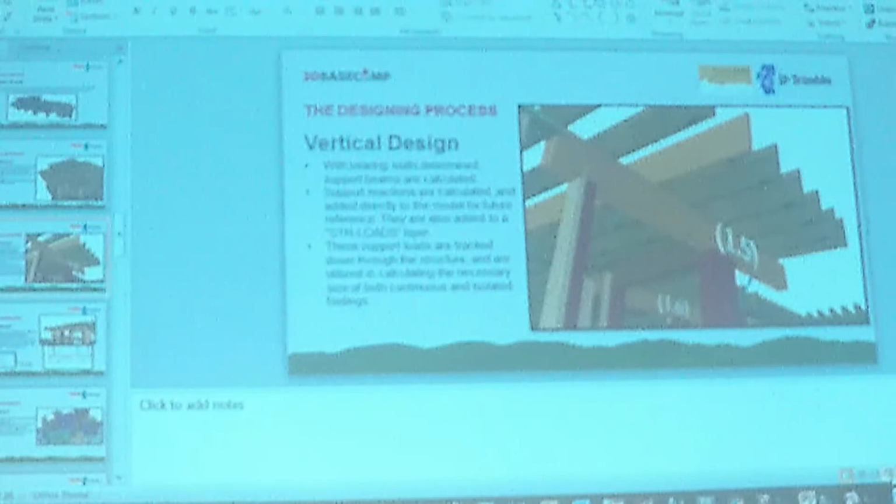All right, back. Hold on, right here. You put all the layers on one layer, layer 0. I saw it just then. Yes. Do you rebuild your layers, or do you just do that for structural analysis purposes? Well, we do the same as Nick. Yeah, I draw everything on layer 0. And then only once it's composed into a group or a component, then it's assigned a layer. Right. So our entire roof rafter system is drawn on 0, made into a component on layer 0, grouped, and then added to a layer. So the entire group's a layer. So one click of a layer turns off the entire roof system.